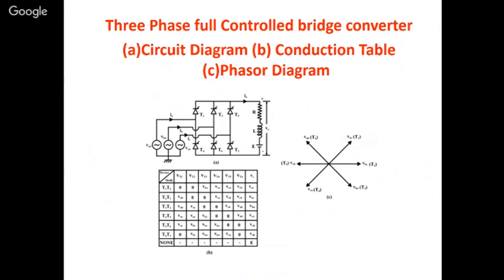The circuit diagram is shown here. So, three-phase full bridge. Mostly in FACTS devices, if you see the UPFC or SSSC, all these use voltage source converters. Voltage source converters are just like rectifiers here. You can see that they can act either as a rectifier or an inverter.